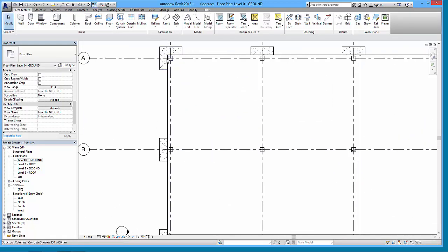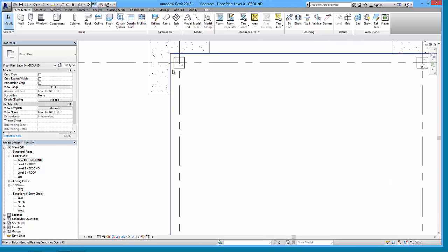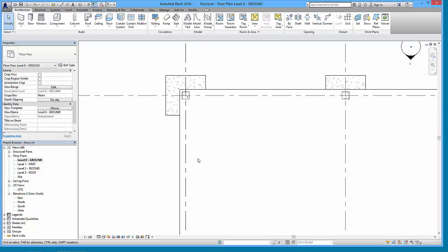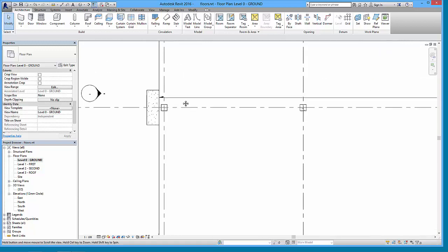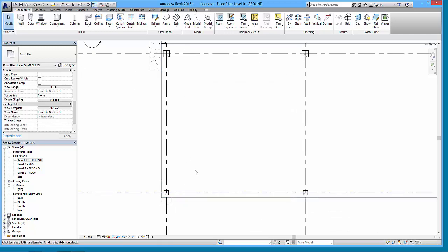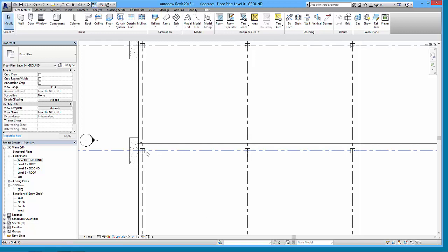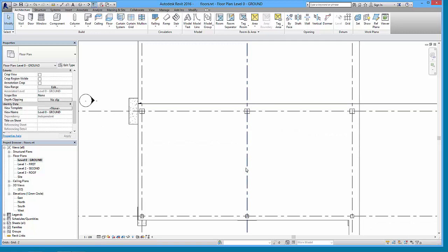And these are our grid lines, and our wall really wants to come along so that the exterior skin hits this line and passes past this column, but we are going to have a problem where the wall just ignores this column and drives straight through it. So I'll show you how to remedy that later on. To start off with, we're going to put some core in, centered on these center lines, and we'll bring it from that point to that point and this point to this point, and similarly there to there, and then we'll copy it up to different levels as well. So I'll show you how to copy and paste to aligned levels.